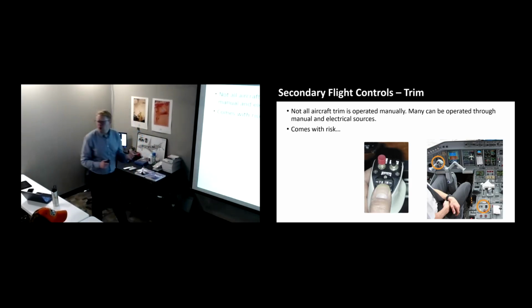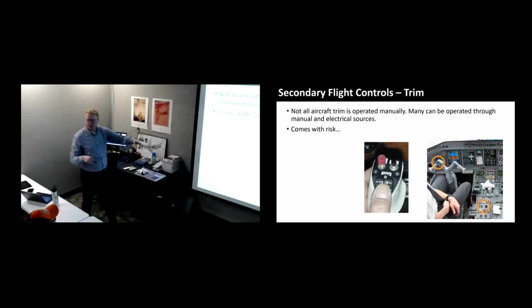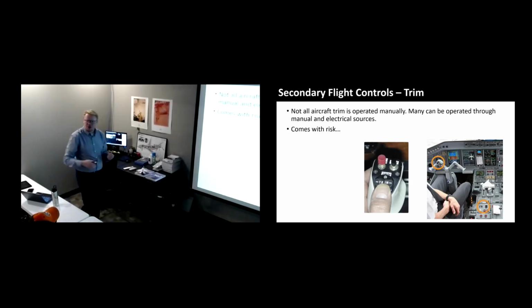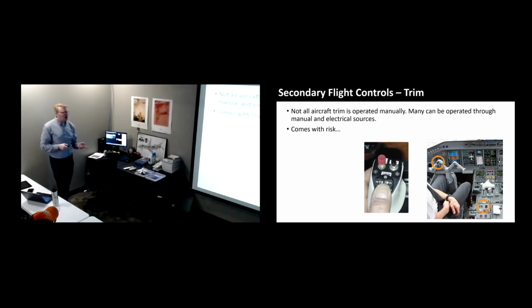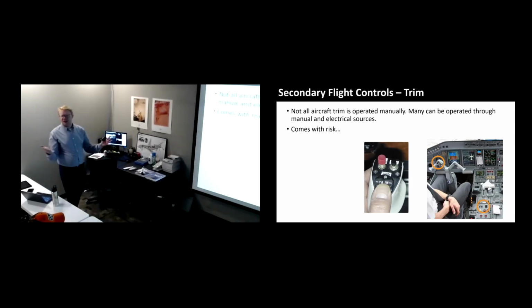If everyone remembers the Boeing issues with the 737, their MCAS system, that was an automated trim setup that ran pretty much a trim wheel for you and did these inputs. Unfortunately, their inputs were not calculated properly and had some issues, but they would accidentally run away and run to the full limit, losing control of the airplane momentarily. It was all a stall protection thing. The airplane monitored angle of attack, and if the critical was 17, they're saying if you get an angle of attack of about 13, you need to push the nose down.